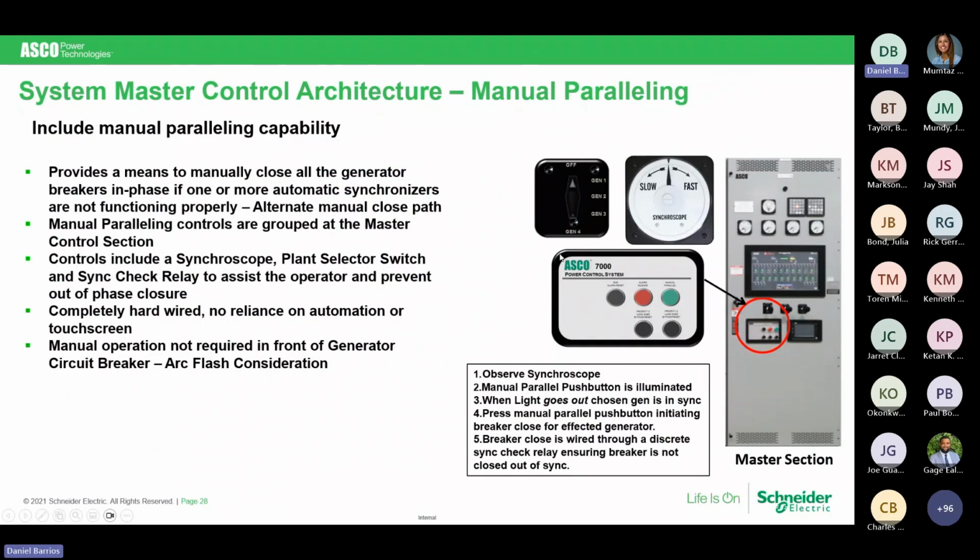The master control architecture and manual paralleling. I even saw a spec recently that still described a swing panel. Swing panel was a panel that if you were standing a couple of sections over, you could swing it over. There were 2 big white lights to it, and you watch that as you were trying to manually synchronize a generator to the other one.